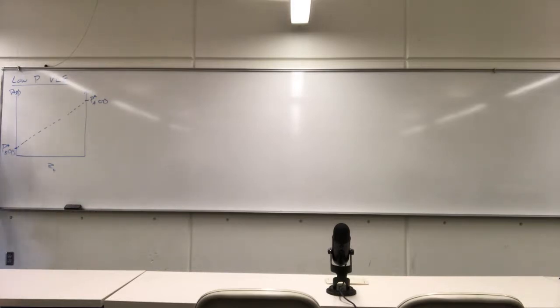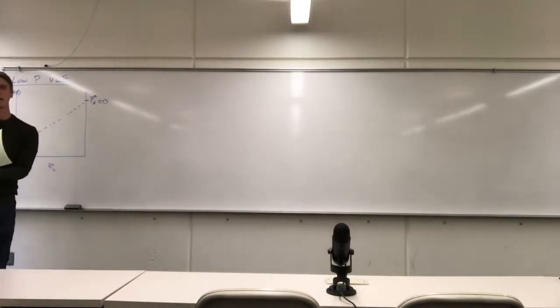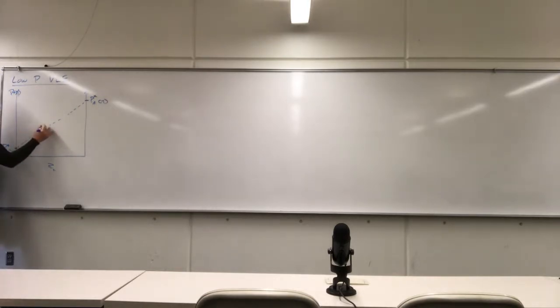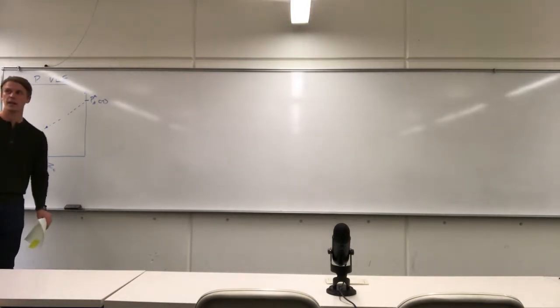Now, the lazy man's way of generating the full phase diagram is to first calculate the bubble curve, right? We're going from the liquid phase to the vapor phase. Liquid is where we're going to have most all the non-ideality. So what we do then is once we know a condition, so at this point right here, I know my composition, I know my pressure, and I know my temperature, which means I have a fully defined system.